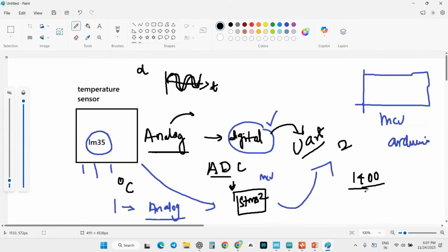And this digital format, guys, it is an external sensor only we are going to use. The external LM35 sensor. Here, the digital format is going to be converted into the exact degree Celsius value. We have to do some math in the code to convert this value to degree Celsius. And this is fine.